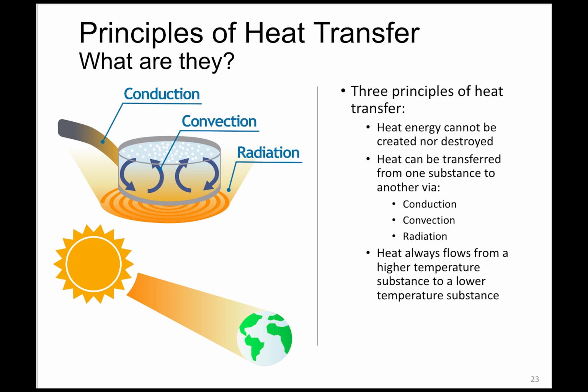Forced convection is when heat contained in a fluid is moved by mechanical means, such as when a fan moves air through a ducted air distribution system. Radiation, for HVAC purposes, can be thought of as heat moving through air by line of sight with little warming of the air. The heat travels to a surface where it's absorbed.